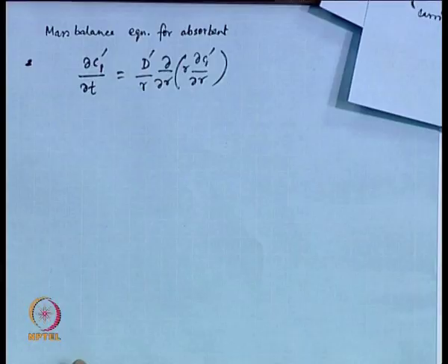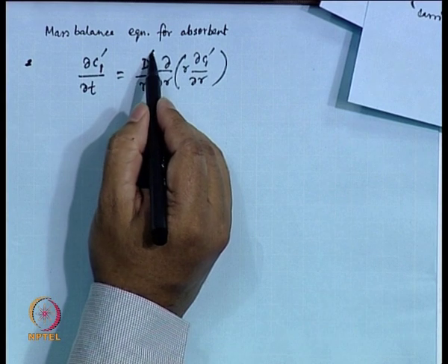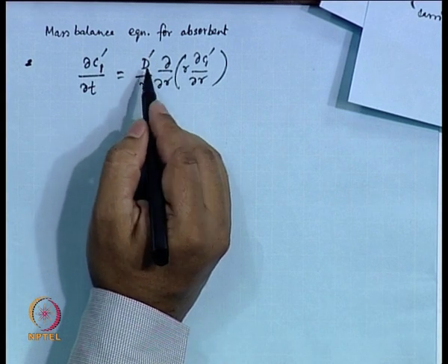But you must have already seen diffusion in catalyst. Anybody who studied reaction engineering has seen the term diffusivity in catalyst. So, diffusion coefficient inside a porous solid is not something new to you, but one thing you must understand is that this diffusion coefficient would probably be an order of magnitude different from a bulk diffusion coefficient in a liquid or in a gas. So, that has to be kept in mind. That is why in fact, I put this D prime. So, D prime is different.